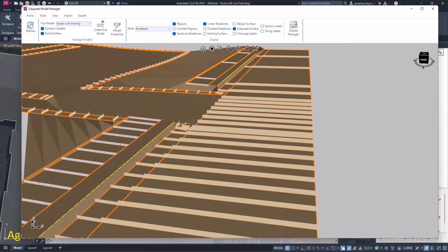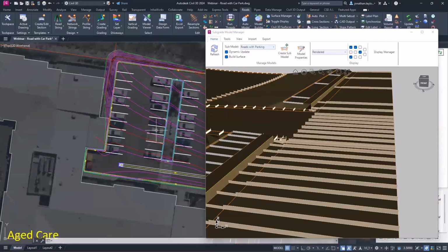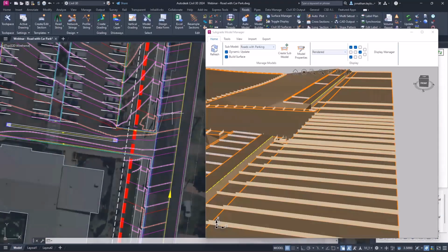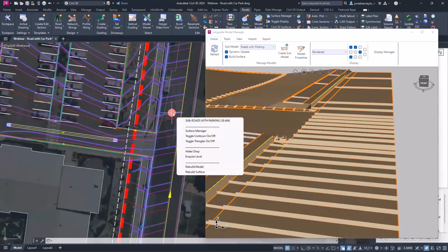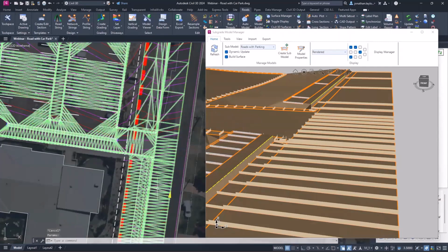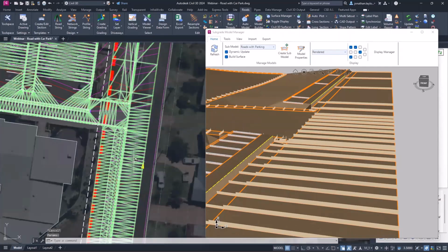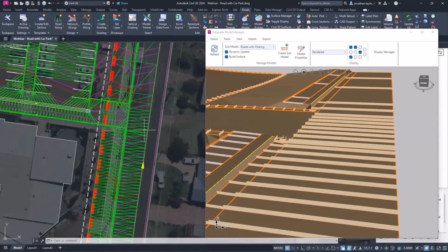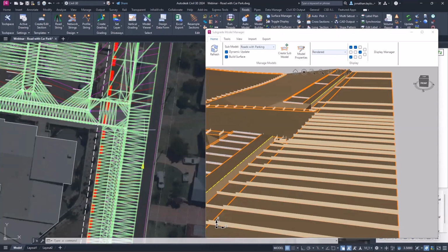So what you may have noticed is when you operate Civil Site Design and you turn on, as we're going to do just here, that subgrade surface? Let's just hover over that. Yeah, so the subgrade surface got created automatically there, so that's all good. Let's turn on the triangles. You'll notice in here that we've got a lot of extra sampling going on. And that's basically because the software, every single meter, will undertake an extra sample for you in the background, okay, to ensure that you get the geometry and the curvature of a vertical curve. Okay, so my section sampling is actually every 10 meters, but I'm getting all these extras.